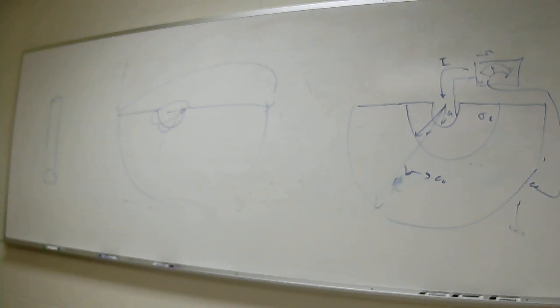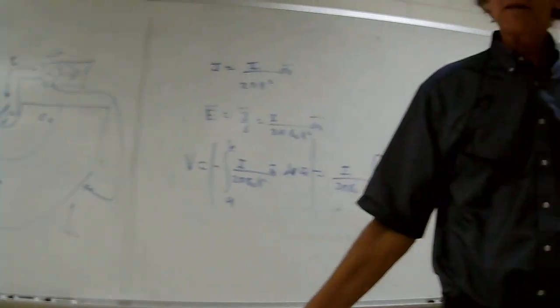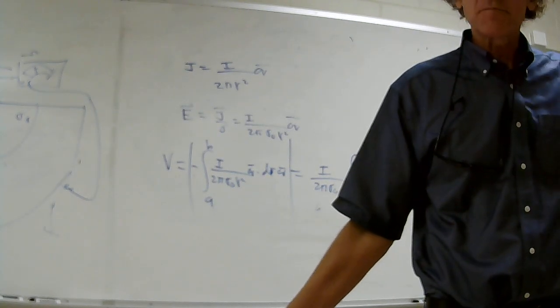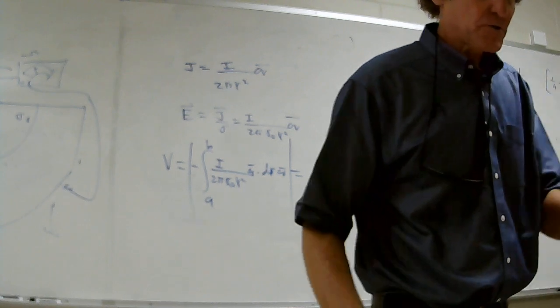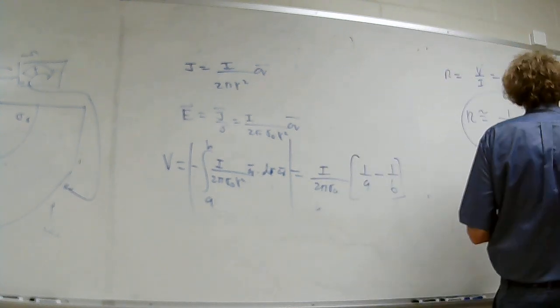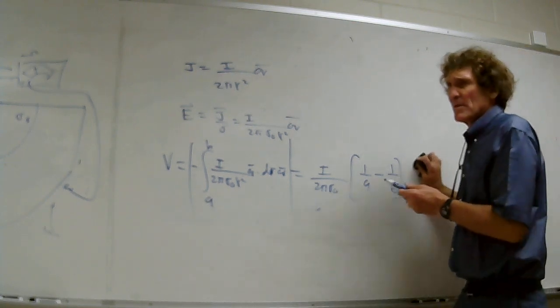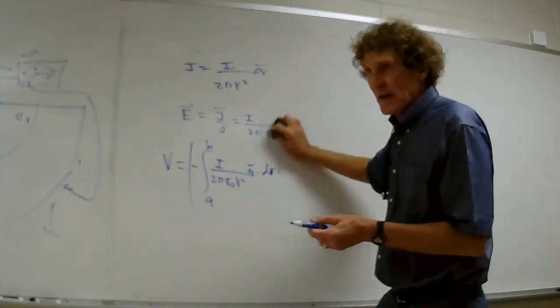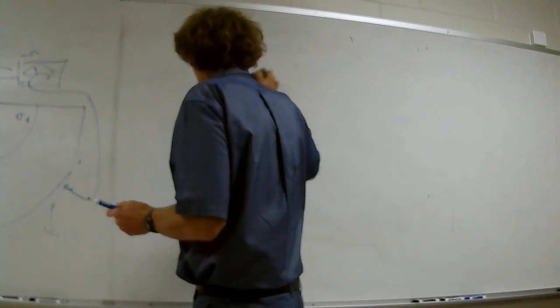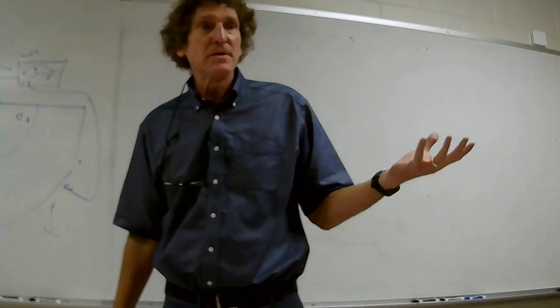And then the time constant, do you remember the time constant for RC circuits? It's e to the minus t over tau. Tau was RC. Do you remember that? We can do something exactly like that for anything where we can approximate the capacitance and resistance and figure out how long it takes that charge to dissipate, like one time constant. I'll show you this stuff, but it's interesting. And by the way, it's very accurate. What is very interesting about a lot of this stuff, even though it looks like gross estimations, is it's actually very accurate.